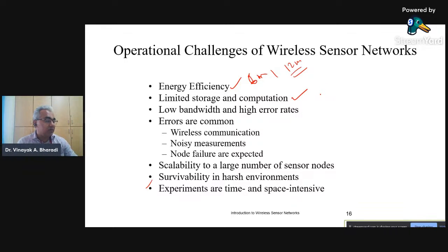We have seen that generally these nodes use microcontrollers. The details of these nodes will come in the coming slides, maybe next lecture. So they have very little, maybe this NodeMCU has less than 2 MB of storage, and some megahertz of microcontroller speed. It has a 3.3 volt input battery, so it uses very little power, and we have to go with that.